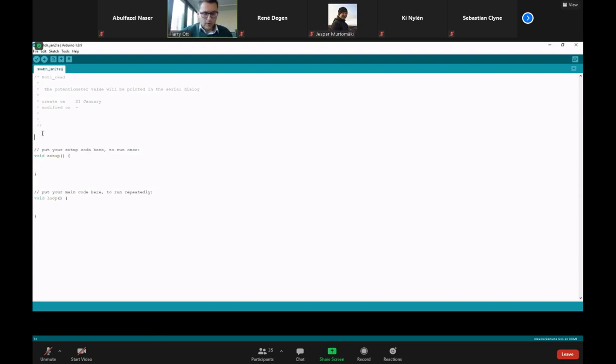So now we can start with the programming. After the comments, we first need the initialization part, initialization of variables. Now we declare or allocate a variable. We will call it voltage, and therefore we will use the data type integer. The command therefore is int, and we call it first variable. No, we call it voltage. It's better.